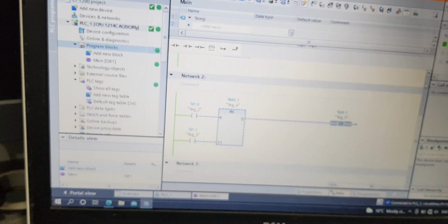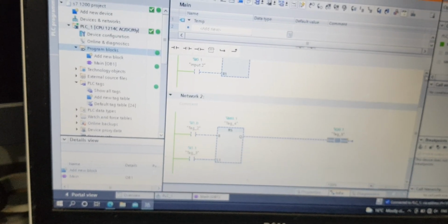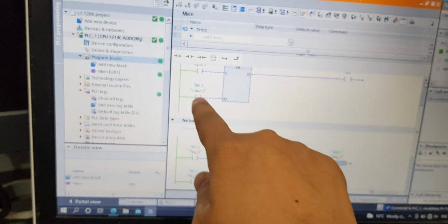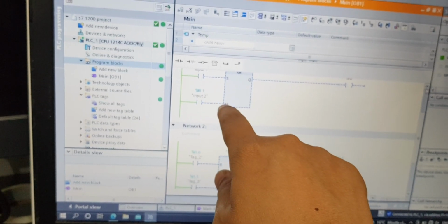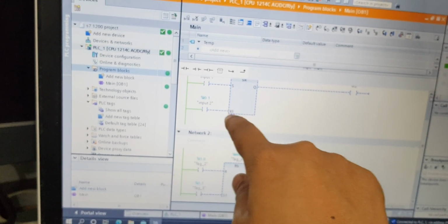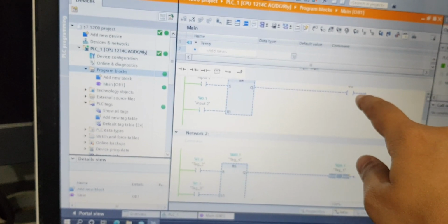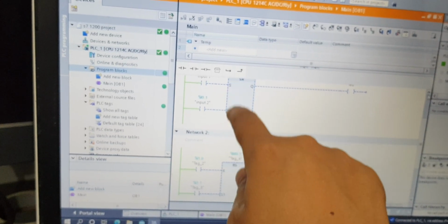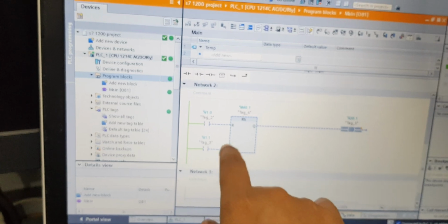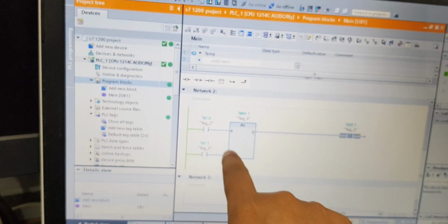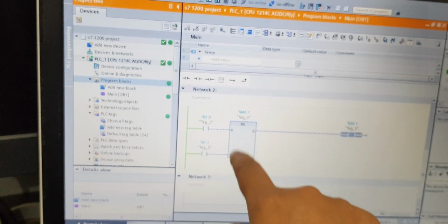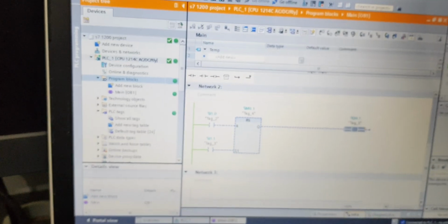So here you can see a simple difference: PLC prefers the left to right, top to bottom rule. So here our last input is reset. That means it goes off when there is the condition of 1 1. And in RS the last input is S, means set. So this will go on when both the inputs are 1 1. This is a simple logic.